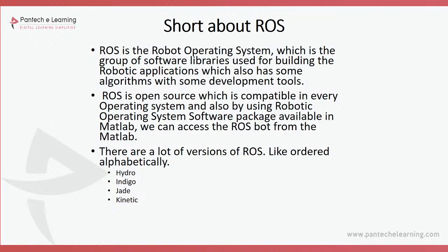So therefore the mapping has been completed inside the robot. Now according to the map, here we also have to make that particular robot move. So whenever the obstacle is matched by that particular robot, here we will be using Arduino as the controller. So through that particular Arduino, we will be able to control the motors either to move forward, backward, left side, right side, or we have to stop the robot.